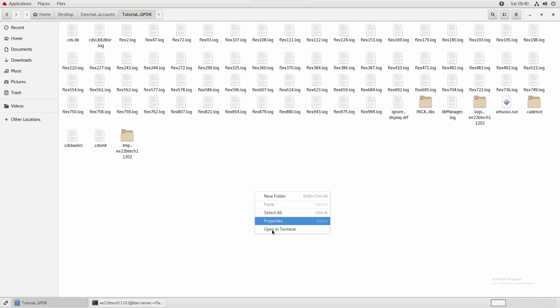So this is part 2 of Cadence tutorials. I will cover how to make schematics. We'll run a small simulation just for the sake of covering that part, but then go into a lot of detail about schematics, how to use them, how to even generate and save SystemVerilog designs, which you can use in your simulations, and hierarchies, shortcuts for making schematics, symbols, and all this linking, etc.